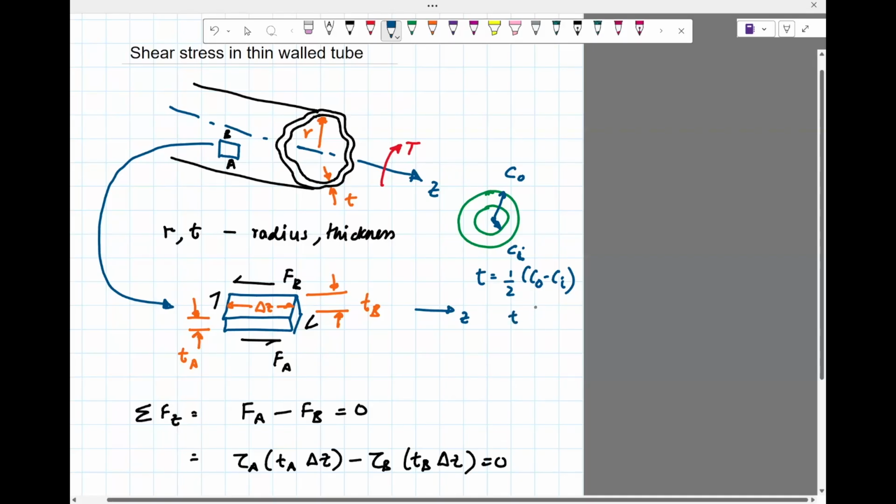If the thickness is much smaller than, this is really heuristic. So when would you use the formulas in this section? When will you use the formulas given in the other section? Well, a thumb rule could be, if T is very small compared to C0, so let's say 5 times T is C0 or 10 times T is C0, then probably you'll use the formulas here.